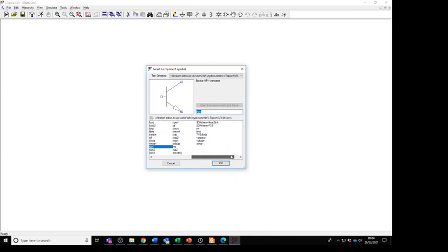And part of the skill, if you like, of LTSpice is understanding what's available and where to find it. It's all there somewhere, and there's lots of stuff on the web. If you haven't got a component, you can download it, and that's the advantage of it, because you can go to any of the major semiconductor companies and download models for quite a few of their chips, and they should then perform pretty close to the real device.